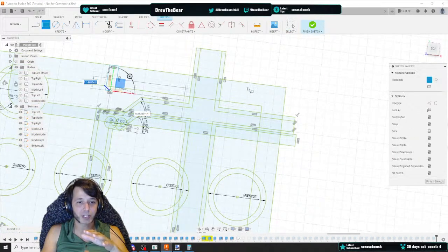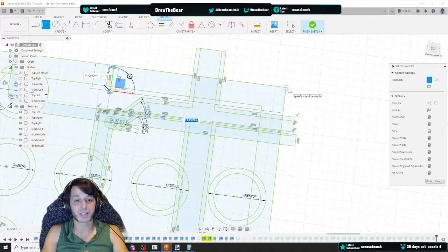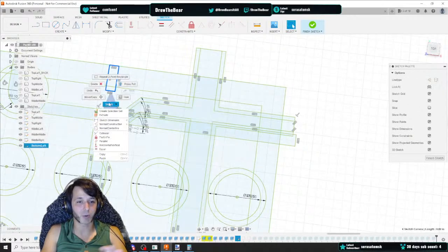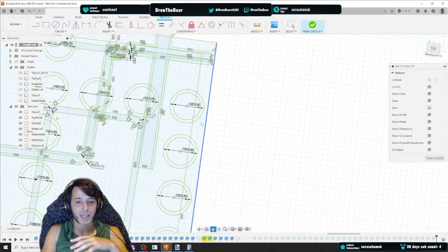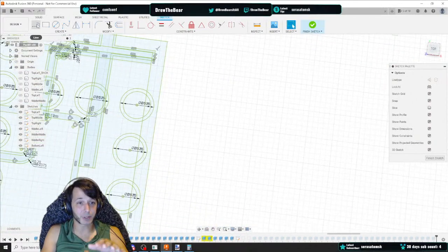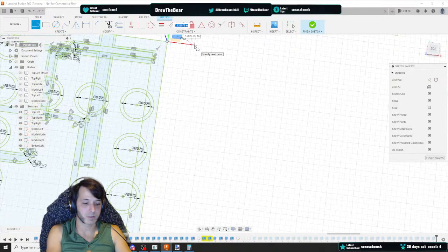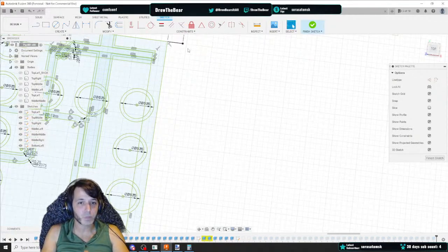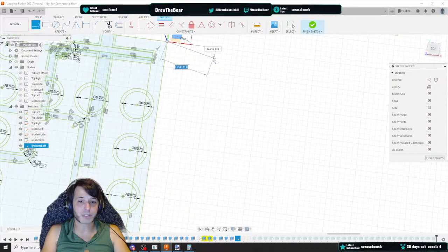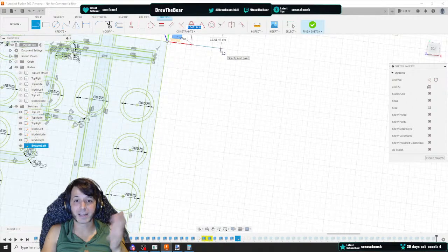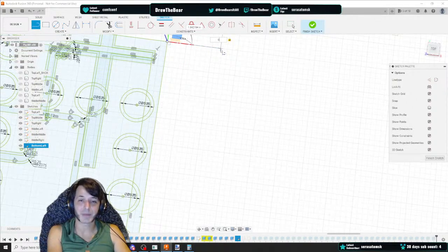If you do the square trick again, you can see that it's 0.2 from the edge in the center of that rod, which is exactly what we want. So we're going to fix it. Then over here, we're going to do something similar. 0.3. Oh, hold on. Okay, so what you may have seen there is that the angle near my mouse is like 12 degrees. That's not 0 degrees. I want it 0 degrees, because otherwise the end of the point will not be in the right spot.